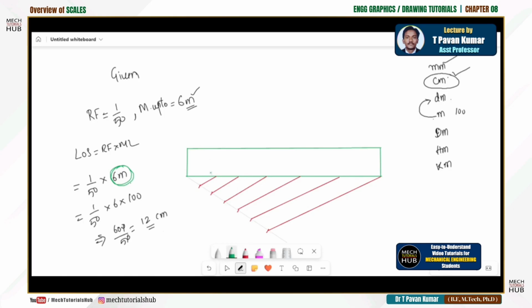Now once you get this, try to project it vertically onto the top horizontal, something like the second division. It went wrong. Third division means we are trying to make some 6 parts of the length of the scale, or else directly you can say 12 divided by 6, whatever the number you get accordingly, but that can't be measured. That 2 centimeters, whatever the thing, if the length is 10 or 12 mm or 15 mm, it becomes easy. If it is a very small division, then it is very tough to draw with a compass. 12 centimeters is fine, you can directly divide it, not a problem.